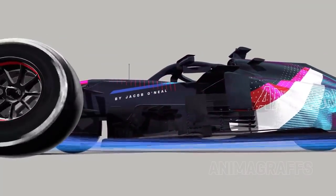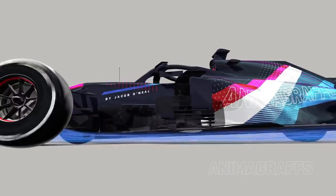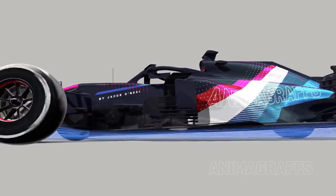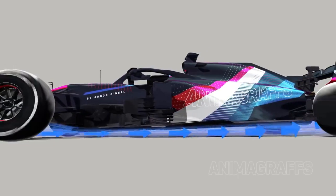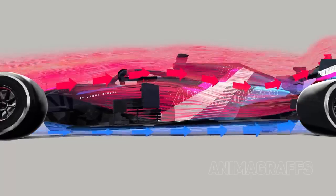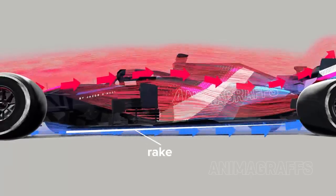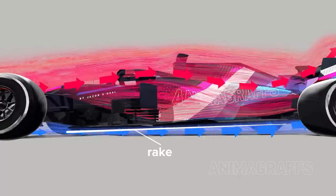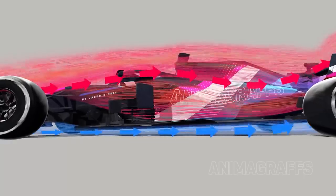The narrow gap between the car floor and the track turns the entire floor into a giant downforce generator as air squeezes, thins, and rushes beneath the car at a different rate and pressure than overhead air. The floor has a forward tilt or rake that creates very low pressure at its narrowest point, but allows air to more smoothly rejoin ambient air pressure as it flows out the back.